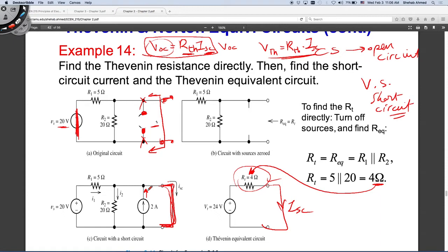There's current flowing from this current source. It's like a constant flow rate pump. A constant flow rate pump will regulate its pressure and keep a certain flow rate. It's exactly the same. It will push current, and internally it has to have a voltage source, of course. But it's a controlled voltage source to maintain a certain flow rate, to maintain a certain current.